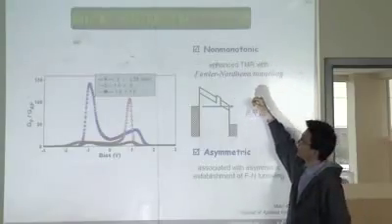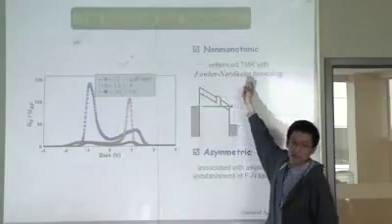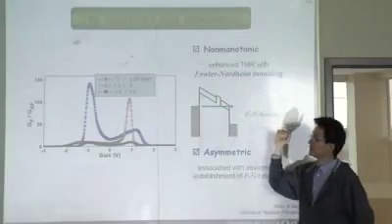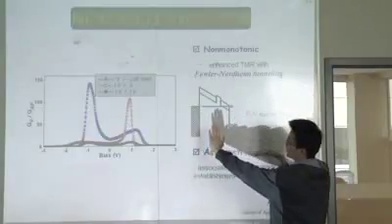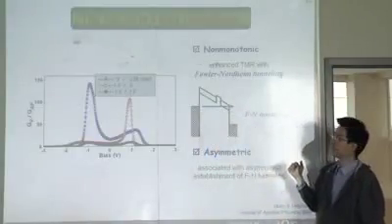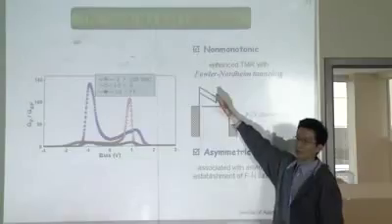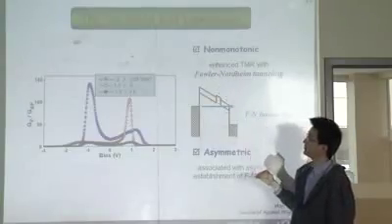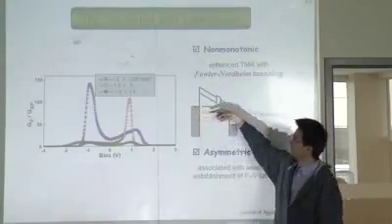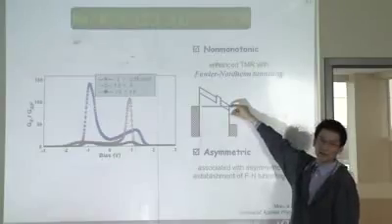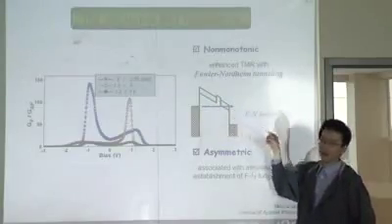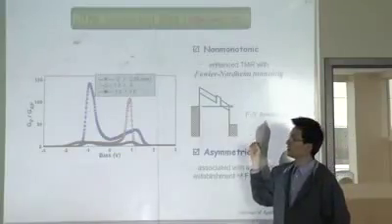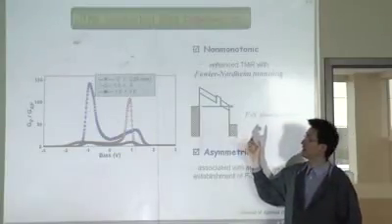This is because of the establishment of Fowler-Nordheim tunneling. Fowler-Nordheim tunneling means, if we have two electrodes and a tunnel barrier, and we apply a very high bias voltage, the tunnel barrier profile will be significantly tilted. When the voltage is higher than the tunnel barrier on the other side, the electron can cross the device by field emission, and its transmission probability will be significantly enhanced.